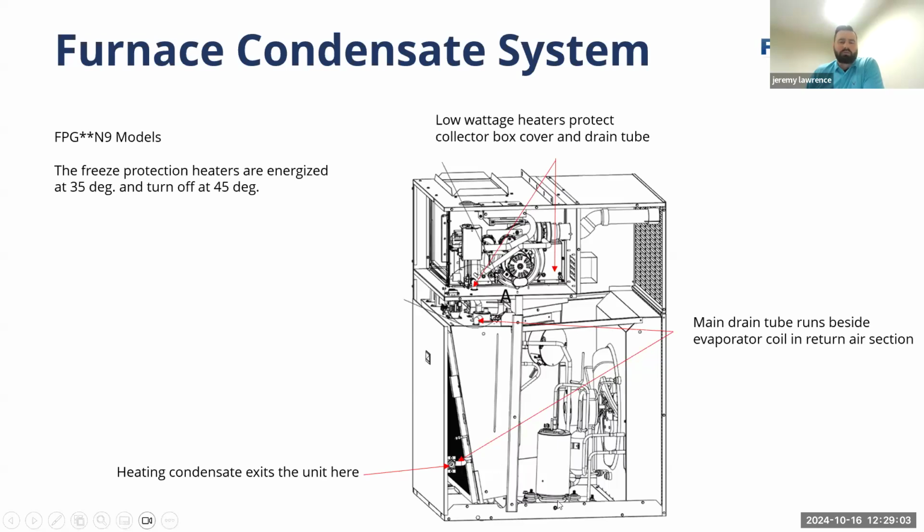This cutaway is a good picture of how the PTACs actually operate, because for the compressor section and the fan, this grill is the only thing actually separating the airflow. So this section of the unit is actually exterior to the building.